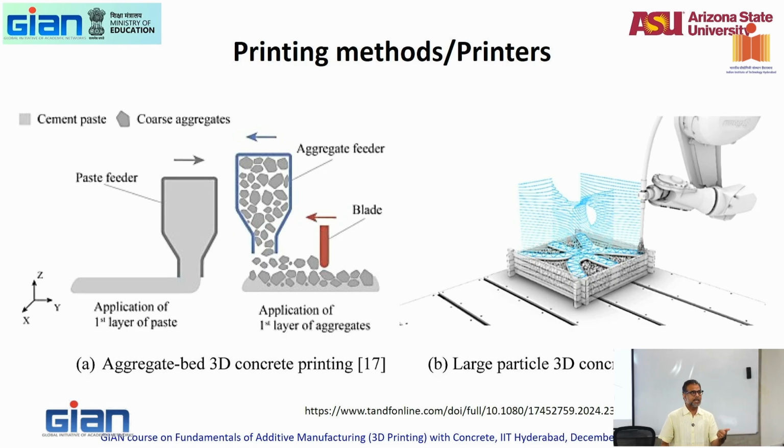Now the loads are added instantaneously, which means the structure should have the strength to carry the superimposed loads without collapsing, which means the fresh state properties of concrete will start to control a lot of what is happening when you print concrete.